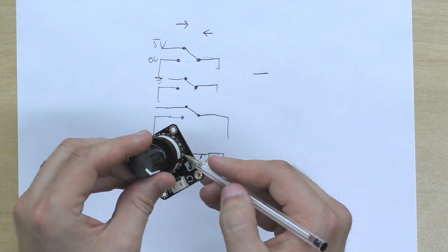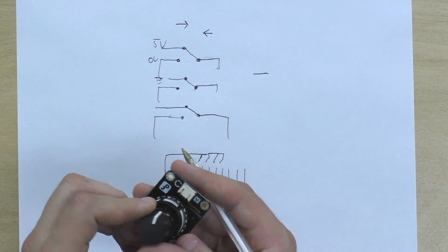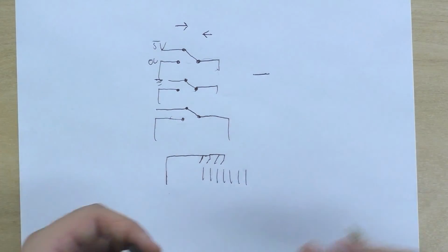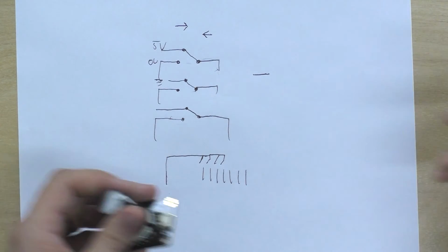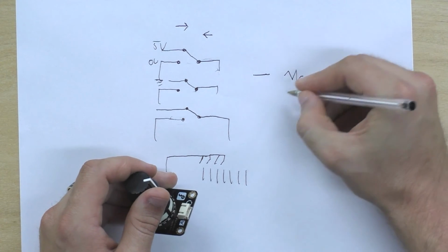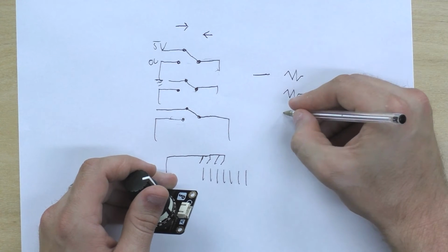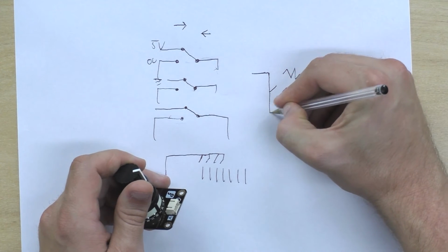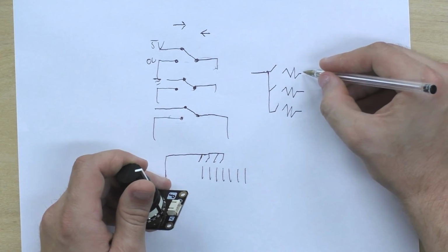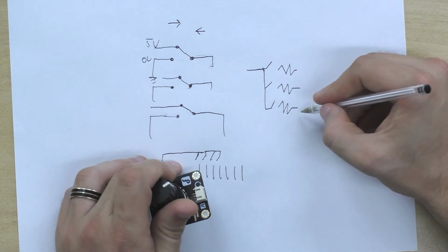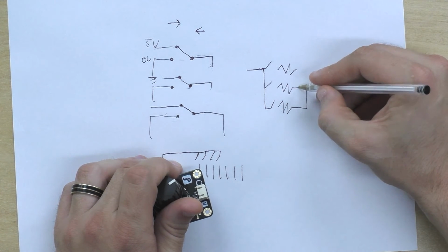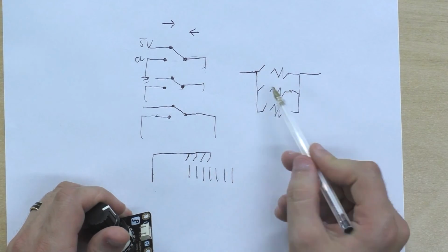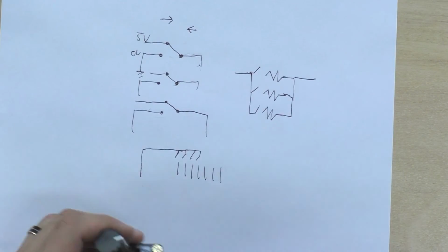You can see the resistors along here, and this is another type of rotary switch. They're not all this way. They're usually one or the other, but there's a bunch of different value resistors here. So let's pretend that there's 12 resistors there. And essentially you've got a bunch of different switches here which make or break the resistance, and these are all tied together. And so signal is going to flow through only one of these resistors, and you have different resistor values, a resistor ladder.